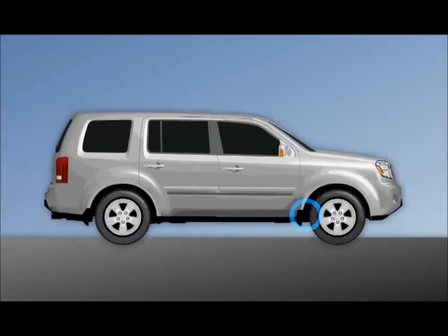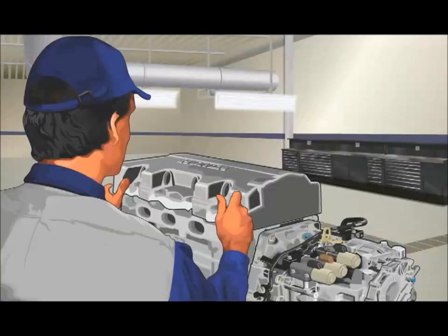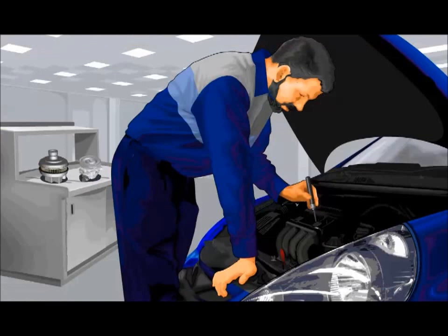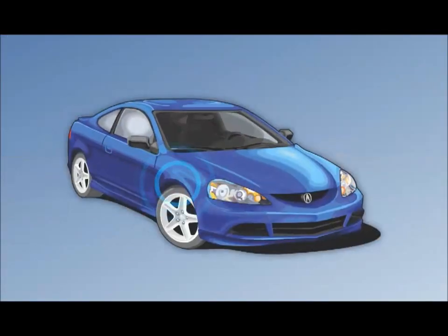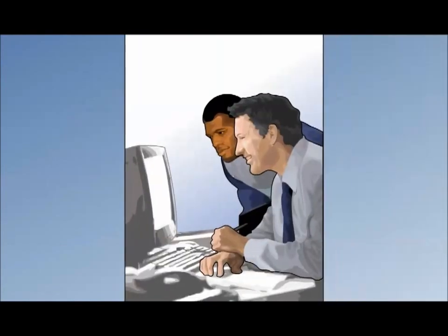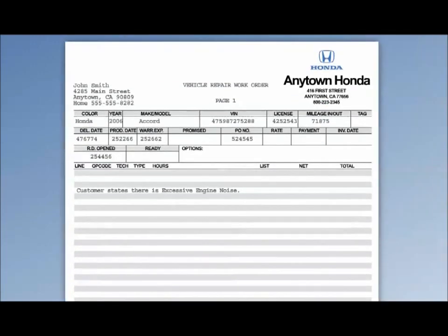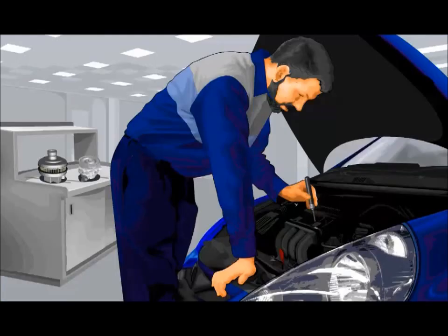Internal vibration problems are created by broken components, either during engine assembly or after incorrect service procedures. If a vehicle arrives with a new vibration complaint after several years of service, first check its service records. Look for engine work such as a new timing belt or a recent transmission replacement. If the car had recent repairs performed, check the work for loose or misaligned parts before any other troubleshooting.